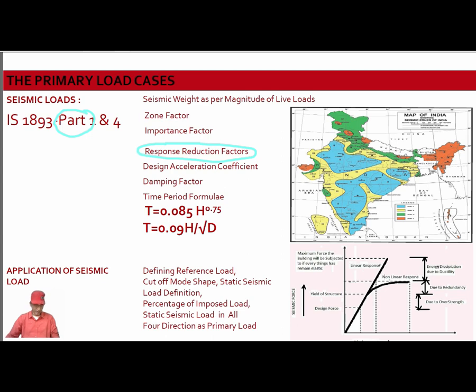It could be a moment resisting frame, a concentric braced frame, or an eccentric braced frame, and it might have been specially detailed for seismic resistance, or it might not have been. As the response reduction factor depends on this, we do not design the structure for the actual seismic load. We actually reduce this actual seismic load by the response reduction factor.